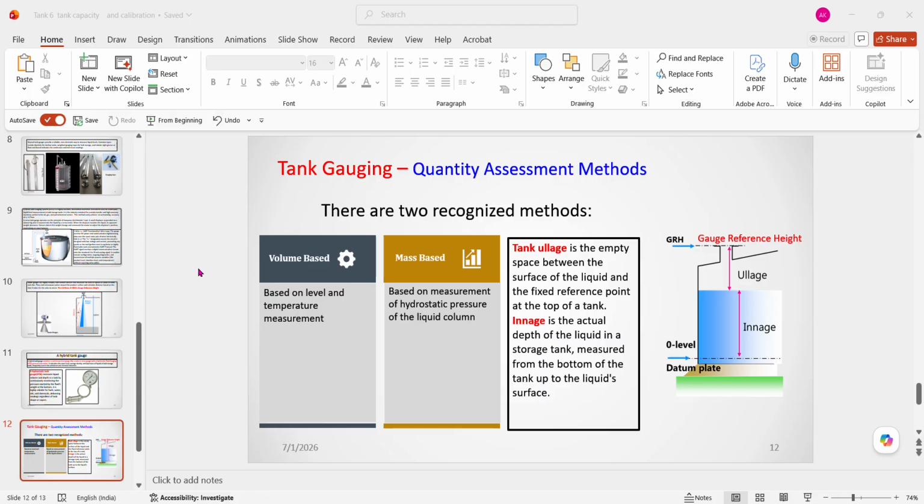Not used for LPG. Floats are not used. High temperature also it can be used. Servo, I have told you. Servo means a combination of temperature correction and mechanical means, where the fluid is not a fluid but balls are there, which move along with the motors, and that is suitable and good for this. Servo is good for crudes, black oils, white oils.